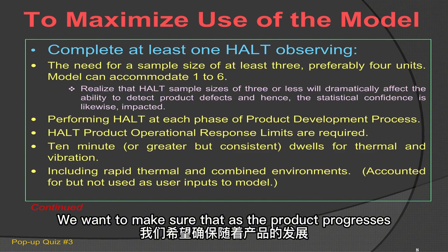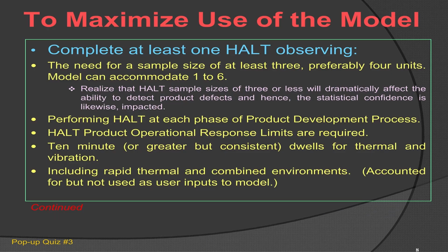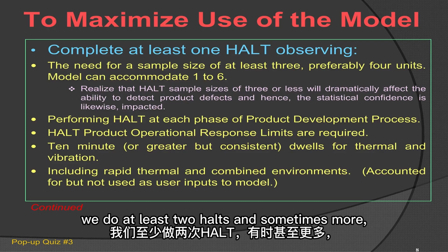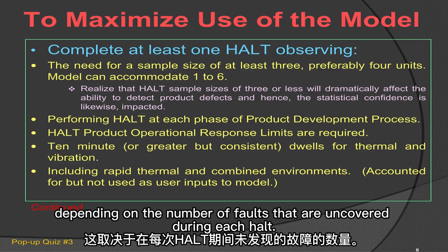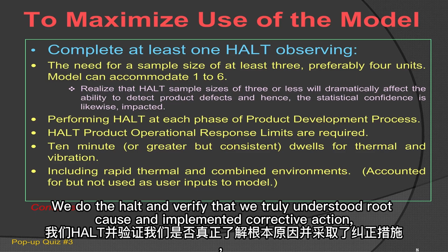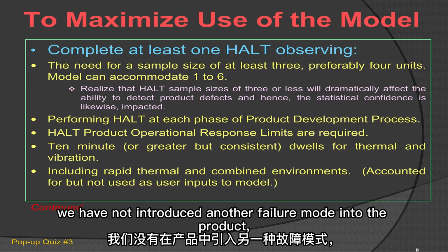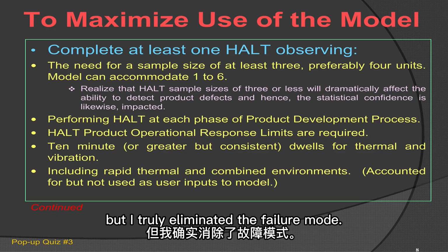We want to make sure that as the product progresses during its development phase, we are performing HALT at each point that makes sense. Here at Advanced Energy, for instance, we do at least 2 HALTs, and sometimes more depending on the number of faults that are uncovered during each HALT. That's extremely important: we do the HALT and verify that we truly understood root cause and implemented corrective action, and that in doing so we have not introduced another failure mode into the product, but have truly eliminated the failure mode.